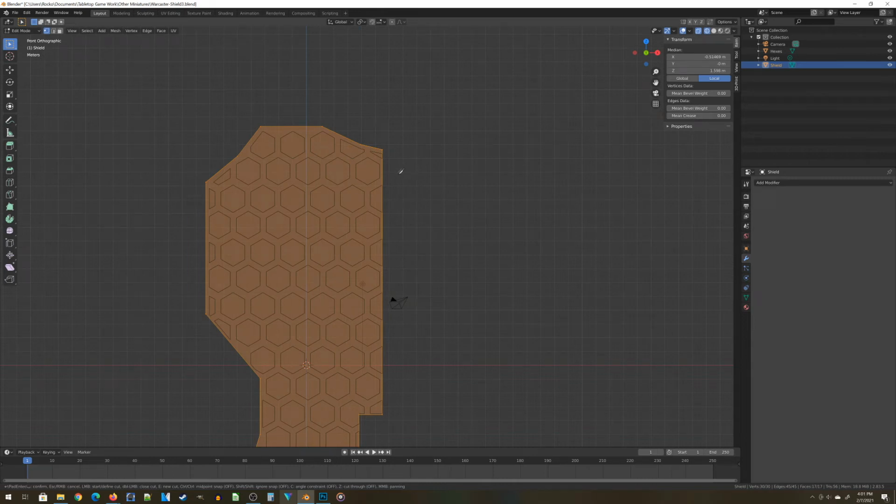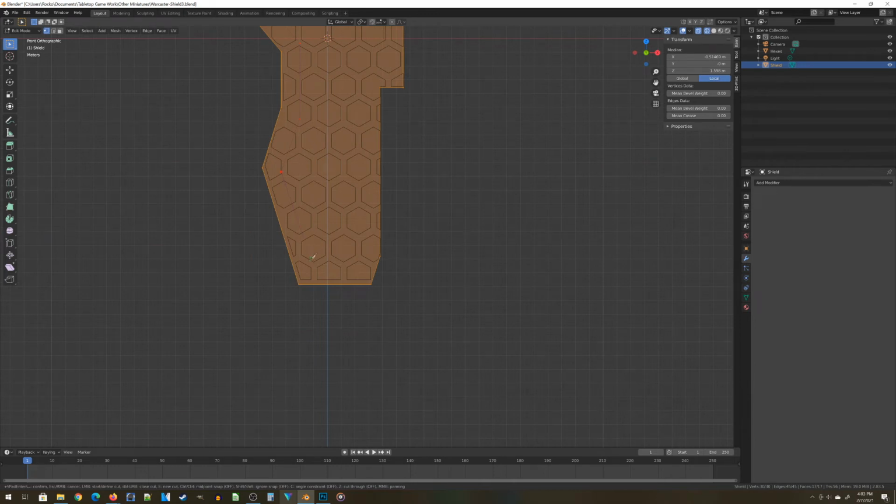So we're going to start the knife operation somewhere out here. And I'm going to try to cut a line such that it follows the outside edge, but the distance from the outside edge is going to be relatively consistent across the entire perimeter. So left click somewhere outside here, and then just kind of follow along the outside vertices, left clicking to create a new segment. And then once you're done, left click once outside the piece, then press enter.